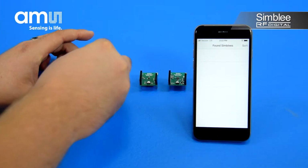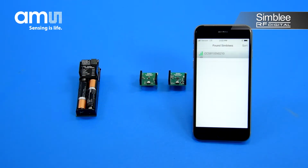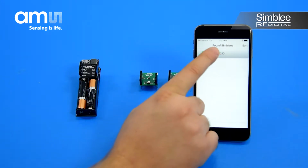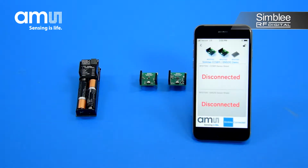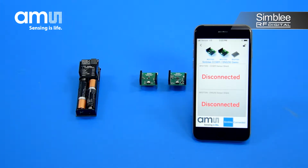Assemble your demo kit with the AAA battery shield and the 7-pin Simblee breakout board, then turn on the switch to power your device. Open the Simblee for Mobile app on your mobile device and select the CCS811/ENS210 device listed. You'll now see the user interface pushed directly from the demo kit to your mobile device. Since both sensors are disconnected, you'll see disconnected listed in both the CCS811 and ENS210 sensor areas on the screen.